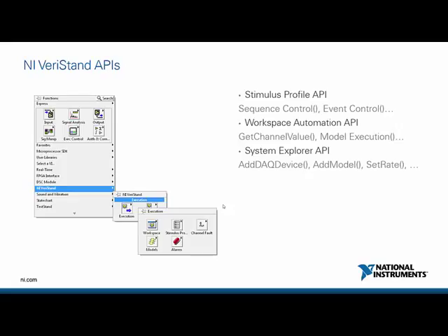And you can do things like communicate with the workspace, automate custom devices, fault some channels, monitor alarms. There's all sorts of different things that you can do with the LabVIEW VIs that are used to control VeriStand. There's an even more extensive list of .NET APIs that you can use with .NET references inside of LabVIEW. It's a very extensive list, and we've had many customers who've been successful automating VeriStand using either LabVIEW or TestStand or anything that needs to communicate through .NET.